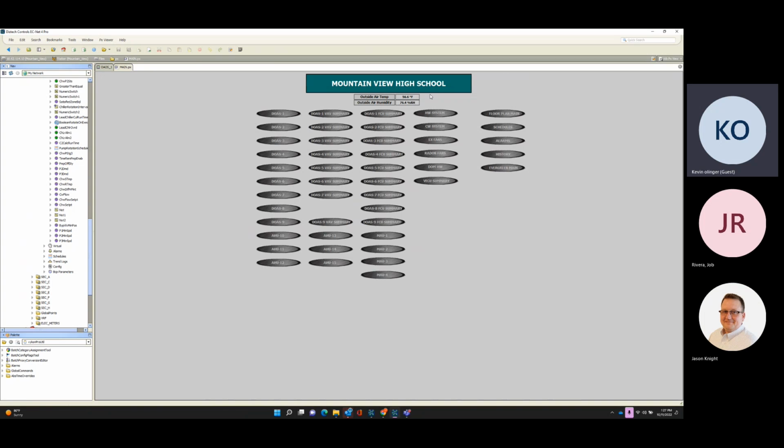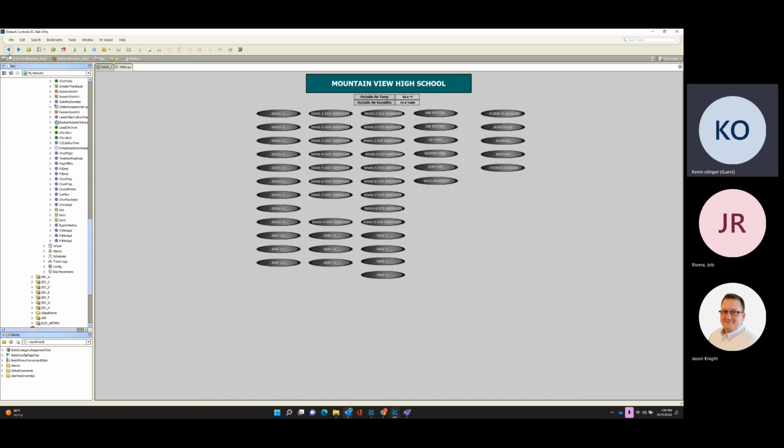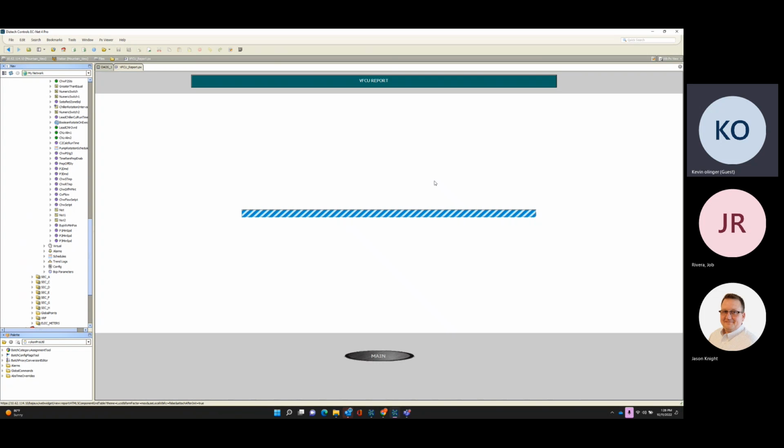Yeah, we definitely want it on all the air handler and DOAS pages, because that's where you get a call from somebody. Let's say something happens and somebody resets the system, so now there's no horns and strobes. And then Randy gets a call because teacher X is too hot, and he goes and looks at her DOAS and says, oh, well, it's off. That's the problem. But why isn't it running? And then he spends an hour trying to troubleshoot.